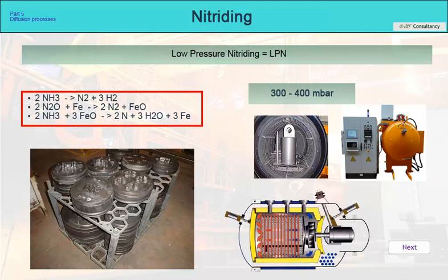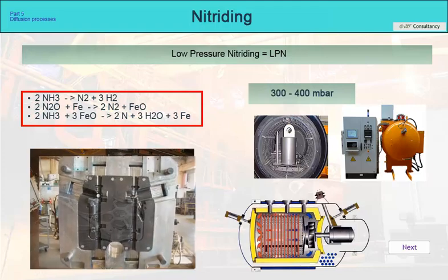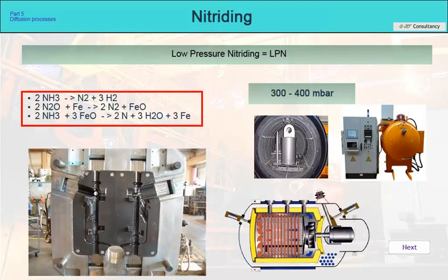However, it is a suitable process for general use, especially for nitriding hot work steels. It is proven and gives very good results for nitriding tools for extrusion of aluminum profiles, but it is also used for post-oxidation of part of die casting dies. It is possible to nitride parts without the presence of a white layer of nitrides, but only for alloy steels, such as steels for hot or cold work.